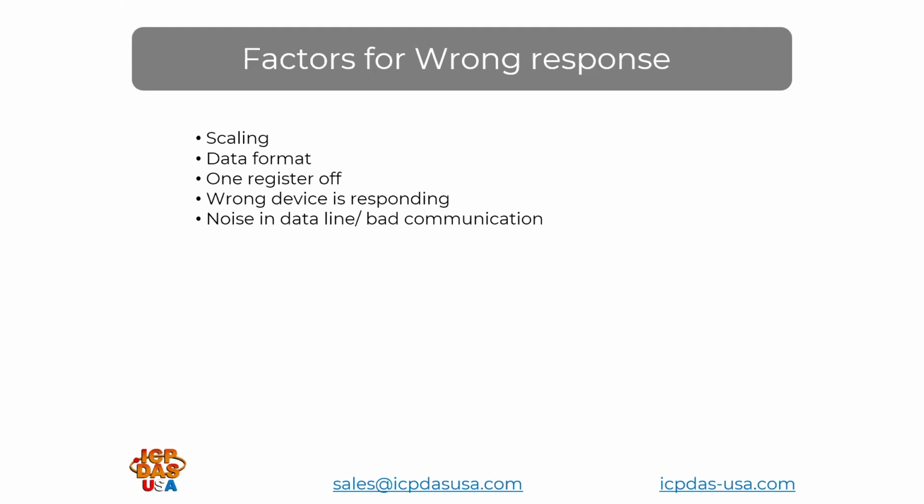And finally, noise in the data line. That's usually a very bad sign. Usually we'd recommend wiring around heavy sources of noise if possible. And just follow standard RS-485 wiring practices.